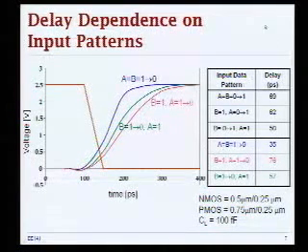Now you can work also the other example for the high to low transition. In this case, you will see a surprising result: if both of your inputs switch at the same time, you have the longest delay. You can work through the example. It's also considering this intrinsic switched capacitance that will give you the idea. Why is it the longest delay?